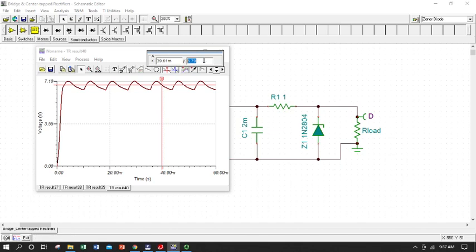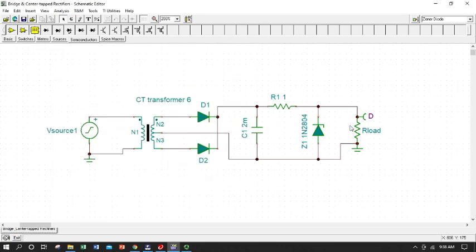Without the Zener regulation, we were losing 10% of our original output voltage. Now, negligible change. Didn't do much for our ripple, unfortunately. There are other things that will take care of that, but in terms of our average voltage output, by including our Zener, we made our average voltage output of our power supply circuit current draw or load independent. So that's the magic of adding this extra component to our DC power supply.